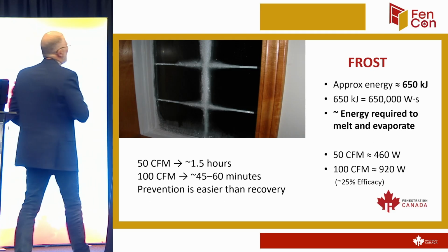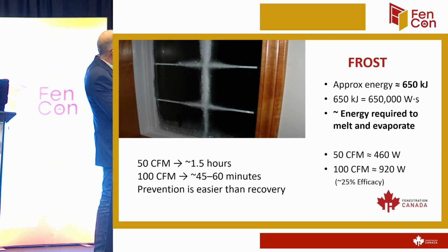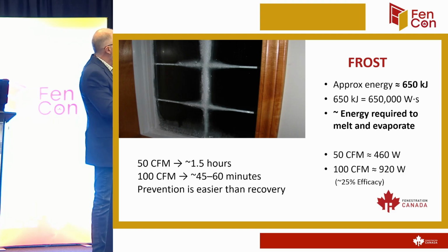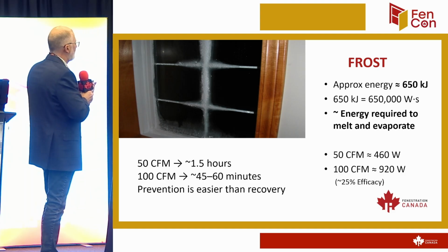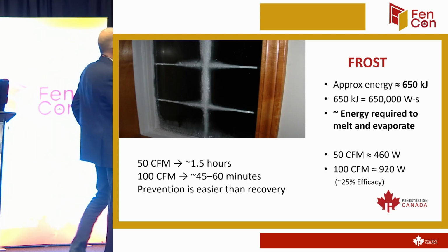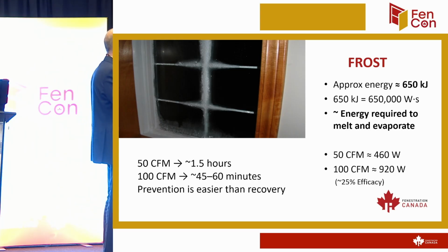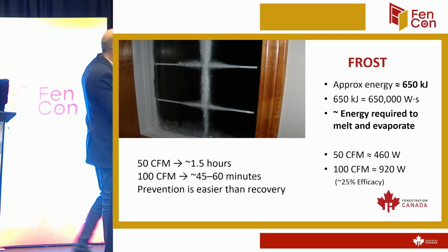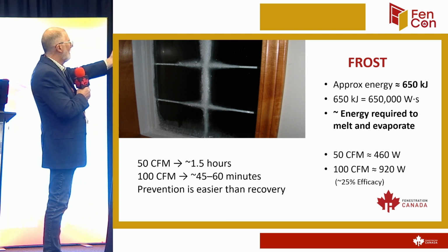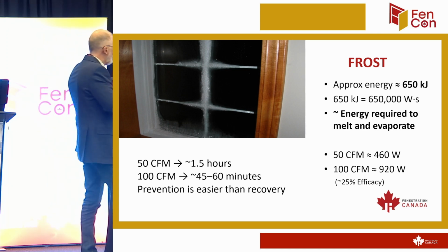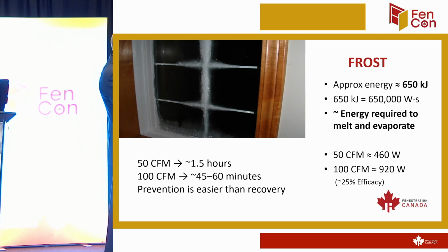Anyway, so you look at frost here, and we convert that. We say, okay, we need 650 kilojoules, which is equal to 650,000 watt seconds, and I can figure out how long it's going to take. With 50 CFM of house air at about 25% efficacy, it's going to take an hour and a half just to get that window back to where I started it.